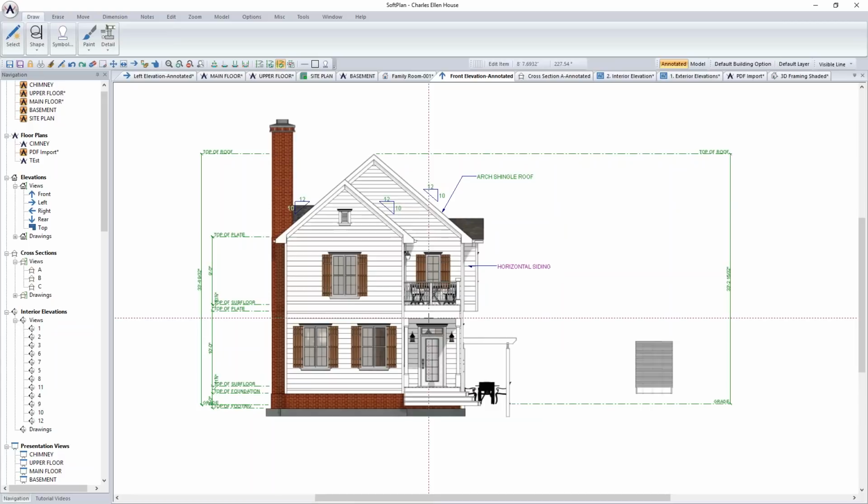We've added a create attic space command. I didn't have time to take you through that today, but basically it's going to automatically generate or place subfloors, walls, ceilings, and room finishes to construct within the attic space of a room cavity. So you've got your attic trusses in place. You'll be able to auto attic and add some of that information in there, like subfloors and ceilings and room mode, etc.